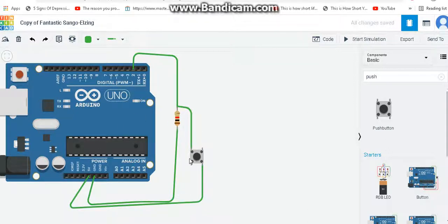When the switch is not pressed, there is no connection between terminal 1B and terminal 2A. Okay, there are names for the terminals. So when you press the button, let's say I am pressing the button, then the connection between terminal 2A and 1B is created. The +5 voltage will go through this path, move to this terminal, and go here, here, here, and pin 2 will become +5 or 1 or high.